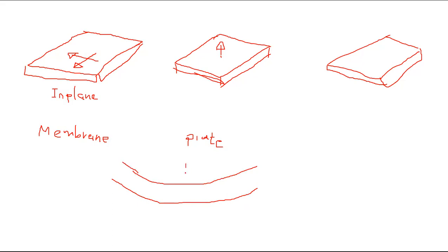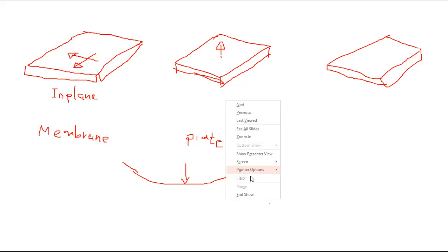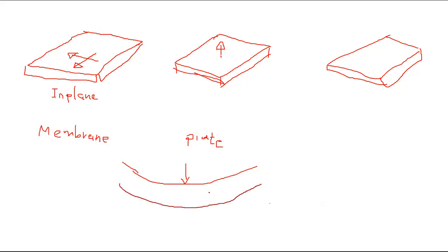we know that if a load is applied, the concrete slab does not take membrane forces. There are no membrane forces developed in the slab when your load is applied. In contrast, there will be stresses like this, top compression, bottom tension, and thus it will have bending.